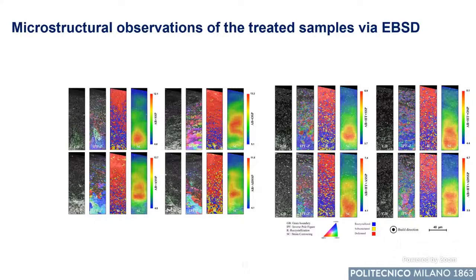These are some other microstructural observations in terms of grain boundary, with and without the treatment, and by applying the different shot peening treatments, severe shot peening, overshot peening, where the damage can be noticed in terms of grain or recrystallization, and then ascending descending shot peening. And we can see that the result is different with respect to the different shot peening treatment we use.